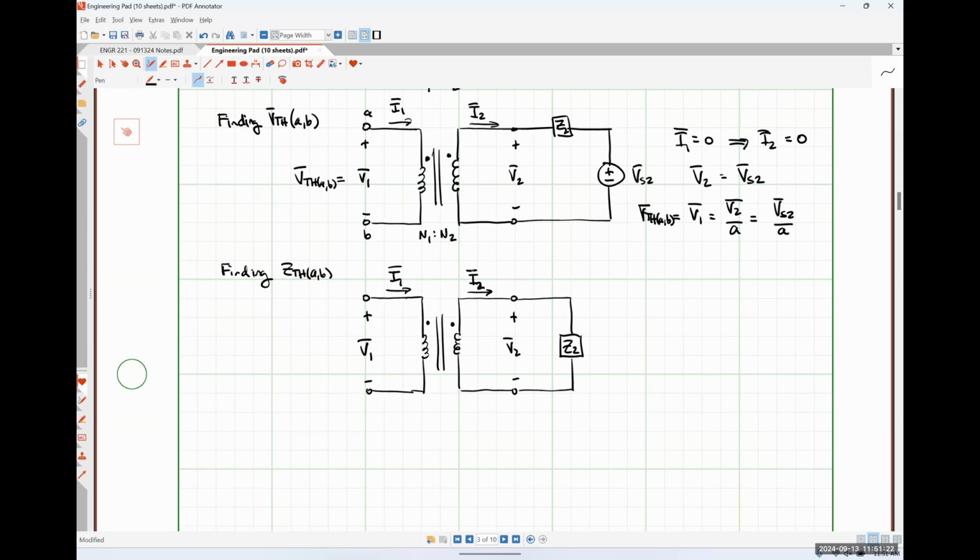So I think that we can apply a test source method to this network in order to determine what the impedance is looking into these terminals. Does that seem fair? So we're taking the same approach as we do when we have a dependent source, just because we don't really know what the impedance of that thing is, but we know if I can figure out the voltage drop across the terminals and the current flowing into the terminals, the ratio of those two things has to be the impedance.